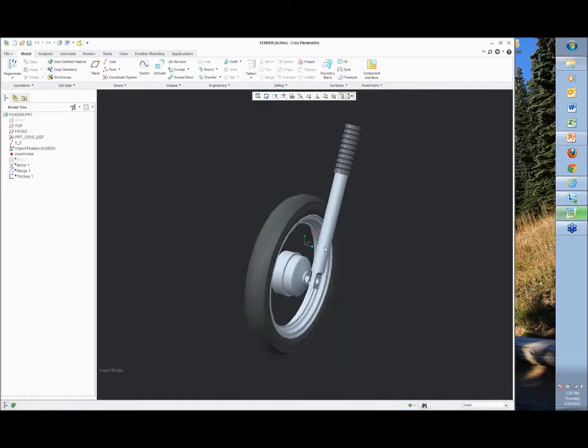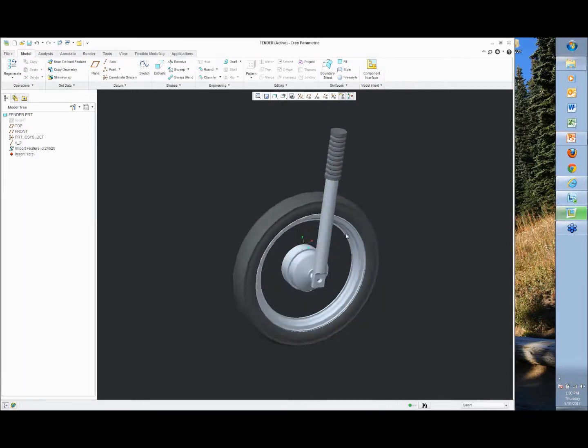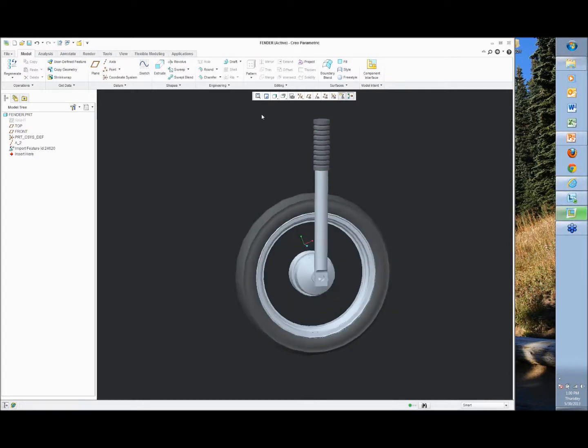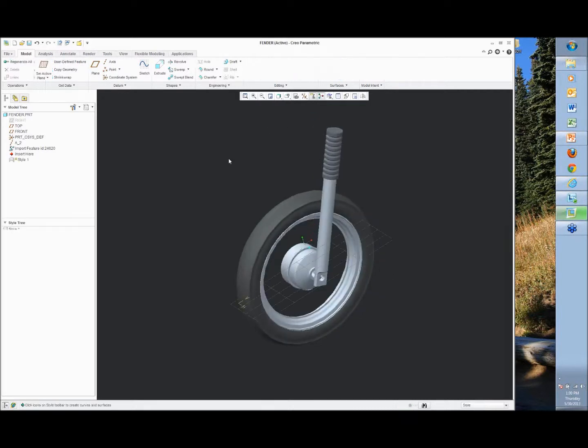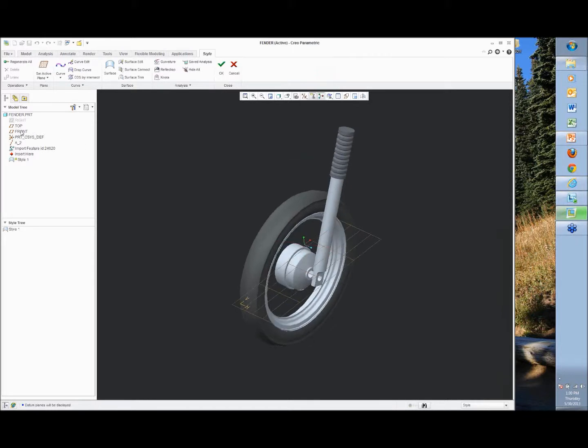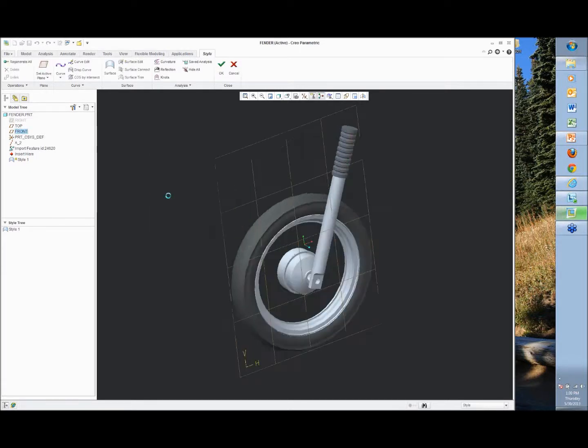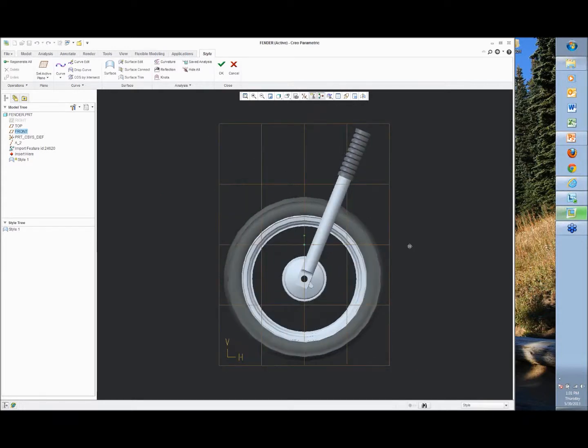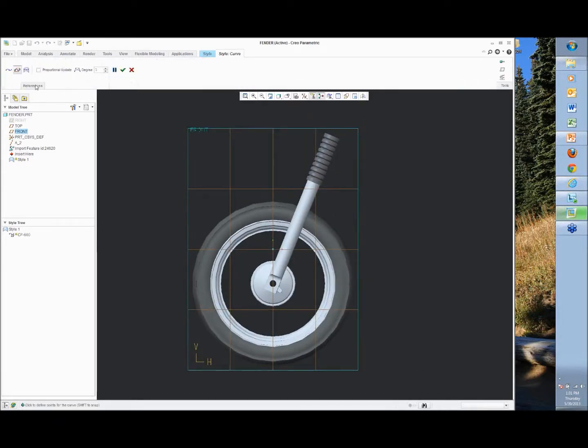All I did here was I imported half of that, so it's just something to see. I'm going to get this stuff out. We're going to make a fender. So we're going to go into the style tool. I set front as the active plane. Start by building one curve. Again, it's going to be curve, inner curve, free, 0. It's going to look something like this.